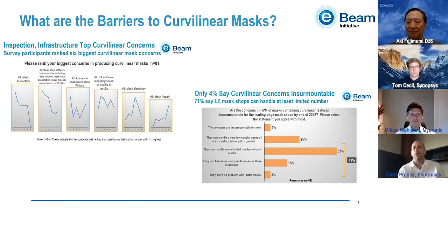So, a small but very important tool in the toolbox for the lithography ecosystem versus something where you start to get an appreciable fraction of designs that can benefit from curvilinear masks. I think the back-end issues, at least on the mask making side, have to get addressed. And that would mean migrating more to image-based characterization and disposition as opposed to, let's call it, discrete pattern characterization and disposition. So that I think is an interesting area to look at for wider adoption here.